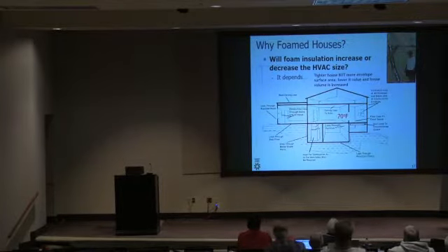Why does it work? Well, all that other stuff we talked about, right? You're air sealing, you're bringing that equipment in and out of that oven for operating temperature, you're not venting your attic in the summer, and it just works as a better assembly.